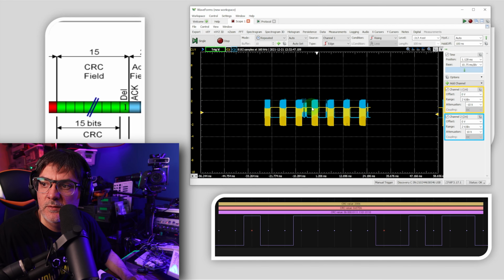And what I want to show you is actually the wheel. Technically, one is for zoom and the other one is for focus. We're going to use 531, filter by ID. Let me clear it up and show you all the information. If I move this, you can see right here, look, I start moving, you see, 6, down, up, down, up, down. And this also changed. This is a very fine amount of information. But yeah, that's how you figure out what each thing is, right? And I'm going to move forward and decode the rest, but at least you know how to decode things on the CAN protocol.